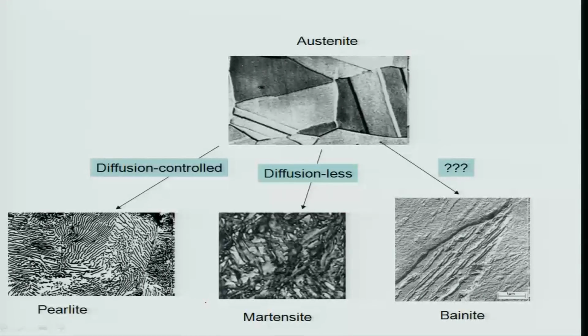Now, while discussing these things, I must bring up a point that in the eutectoid transformation, the most important thing is the gamma phase, austenite. After giving you a description of the phase diagram and also a little bit of the microstructural features of cementite and pearlite, I just wanted to go back and tell you what are the host of microstructures which we can obtain in a steel and how we can do that. That is the basic purpose of this slide.